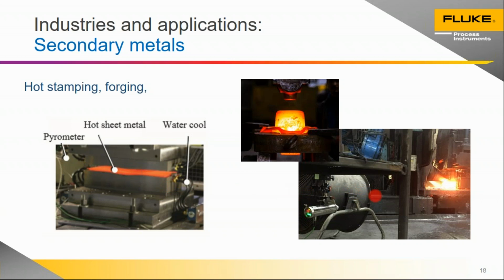In this lower right-hand view, you actually see an Endurance pyrometer located pretty far away from the forging operation that's going on there. In this case, despite being halfway across the room, we were able to get just about an inch or so spot size over at the part, looking near the bottom as it was rotated and being worked. But what the customer ended up doing instead is using one of those fiber optic units, and he was able to position that fiber optic unit right inside this forging machine, where it could take the nastier environment and keep the electronics safely away.